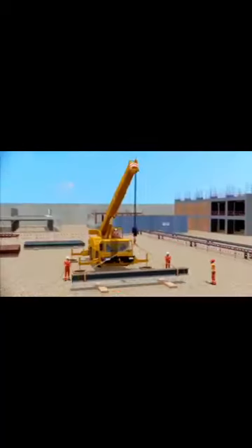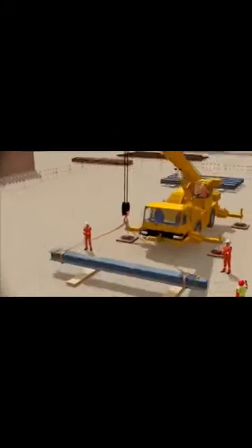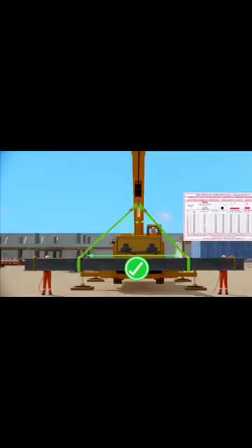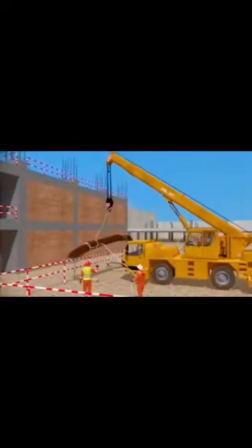If the angle of sling triangle is bigger, it will create more pressure on the sling. This will reduce the capacity of the lifting weight. Make sure that the angle of the sling triangle is smaller, which will increase the capacity of lifting weight and is a safe condition. Lifted weight should be properly tied up by the guide rope so that it does not hit any person or object. Do not use equipment in any extraordinary and adverse conditions, such as strong wind, heavy rain,